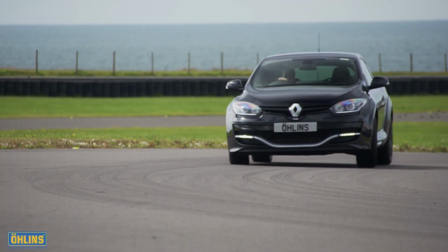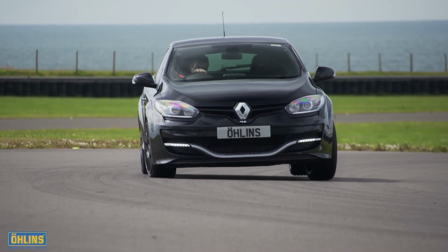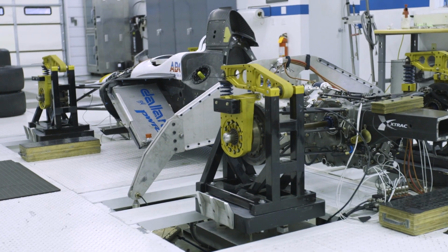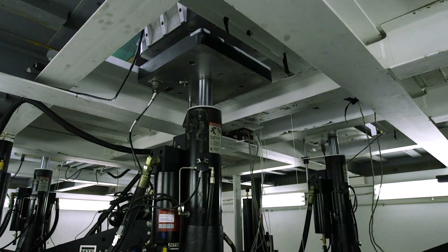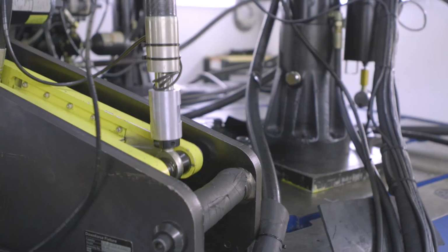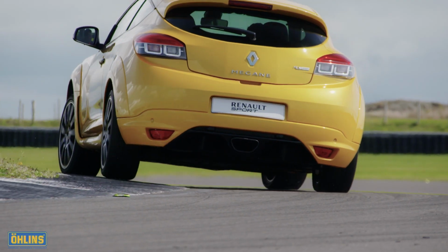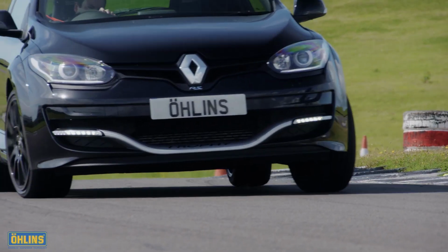We take the data that a vehicle has obtained from going around a particular racetrack and then upload that data into our computers. With that data, combined with a computer model we generate by measuring how the car behaves on the rig, we're able to determine how we should push, pull, and shake with our 7 shake rig actuators. This makes the suspension move in the same way it did on the racetrack.